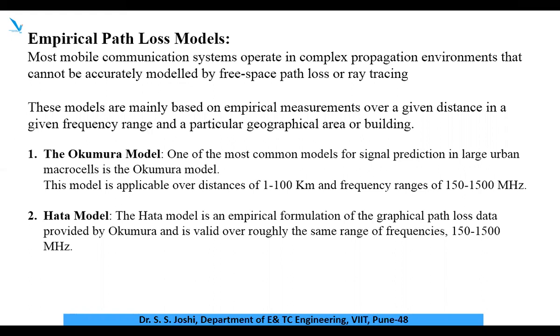As distance increases, your power decreases. Frequency, lambda is there, so as your frequency increases, your wavelength decreases, so definitely at high frequency your power will decrease. Try to relate all these parameters in that particular equation. Similarly, the geographical area will decide the model, that is the 2-ray, 10-ray, n-ray model or a generalized model. Depending upon the geographical area, your signal strength changes, and because of that you require some empirical studies and